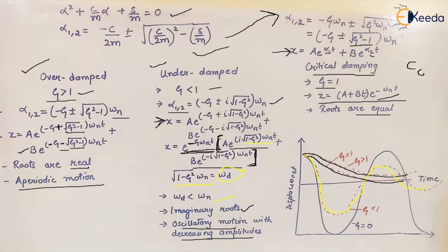Now in practical cases, we always keep the damping factor somewhat greater than the critical damping. We actually want critical damping, but we have to keep into consideration that at times, because of temperature variations or other factors, the viscosity of the fluid may change. So it will actually bring the condition to the underdamping situation where the oscillation will be there and along with that damping will take place. But we don't want that. Rather we want the system to stop or the damping to happen in a very short duration of time without any oscillations, right? So we always keep this damping somewhat greater than that of the critical damping.